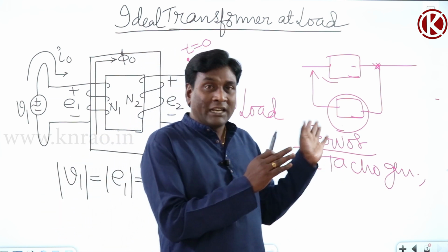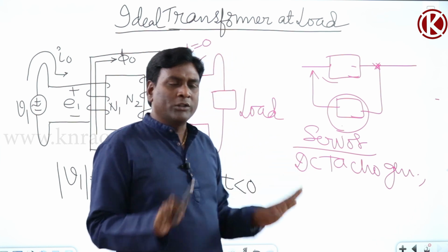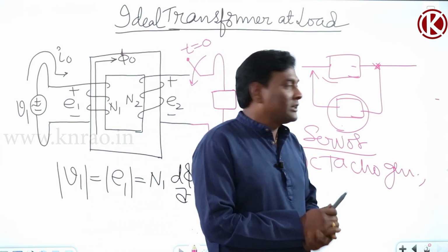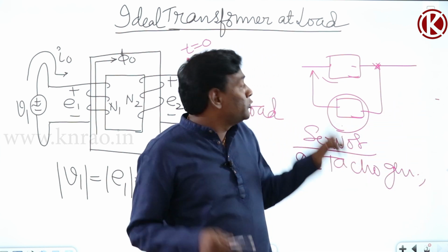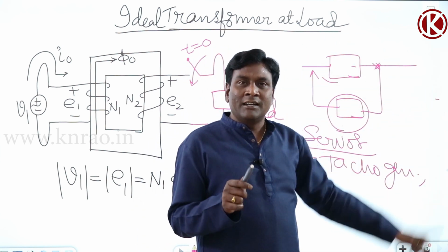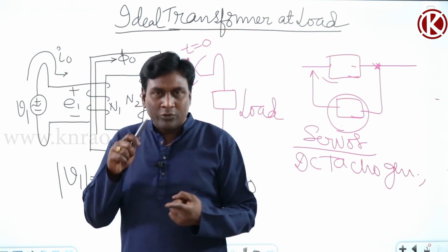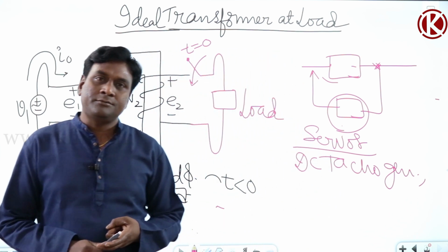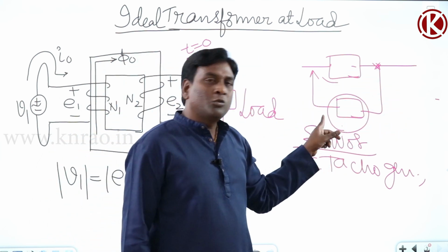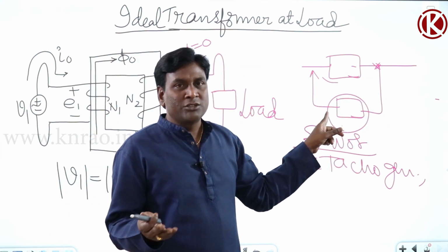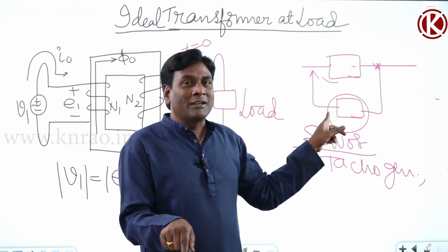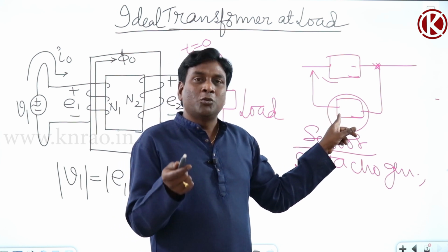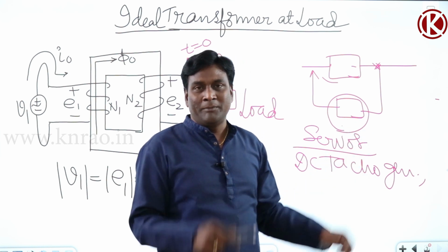Of course, I'll give one more example now. Basically one conclusion: machines are supposed to work under steady state conditions most of the time, handling the bulk of power. For that, steady state behavior matters, losses matter, efficiency matters. For the feedback path of the control system, servos or measuring instruments will not handle power, so power loss doesn't matter, but they will handle information, so time constant and transient behavior matter.